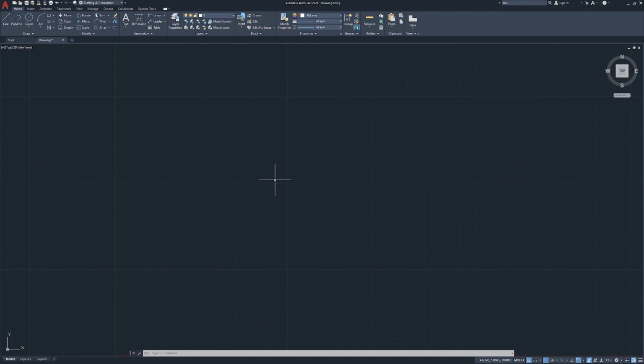So if you needed to do something that was very blocky, say a square building with square rooms, that's what you would use snap mode for. You would match snap mode to your grid mode, and then you could snap in any increment you want. You could make these grid squares an inch, you can make them a foot, you can make them 100 feet if you wanted to. They could be 2.5 feet if you're feeling spicy. Might get you into trouble, but it's good to know.